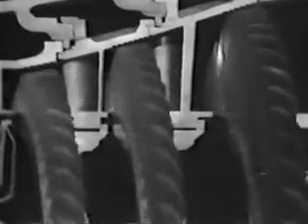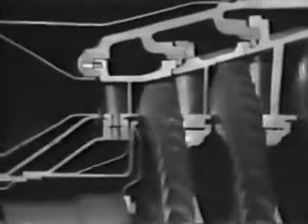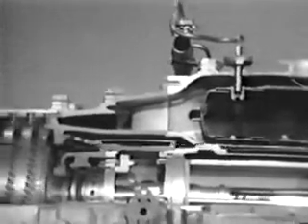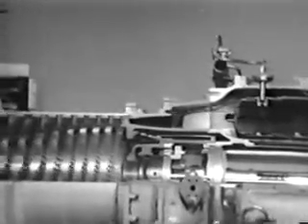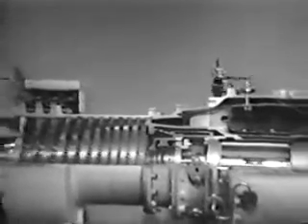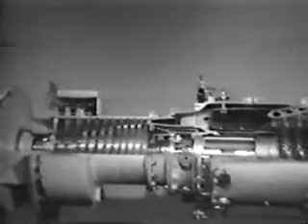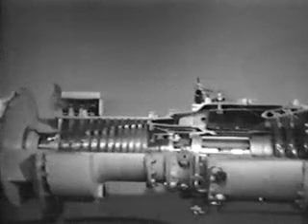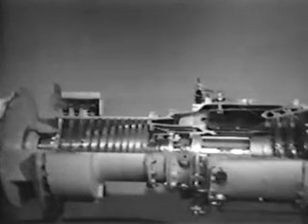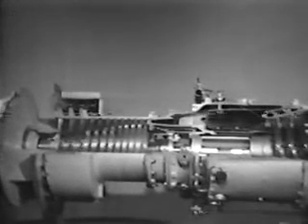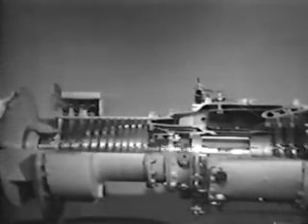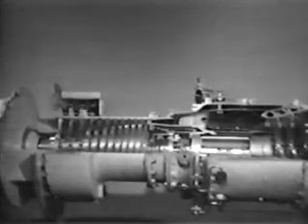You have seen how compressed air and fuel are combusted and how this rapidly expanding hot gas is used to turn the turbine rotor. Smooth operation is achieved by transferring some of this power into further compression of air. The turbine engine is a heat engine, converting heat energy into power. Each of the 4 processes contribute to the uniform performance of the engine and will be examined in more detail in the remaining lessons of this module.